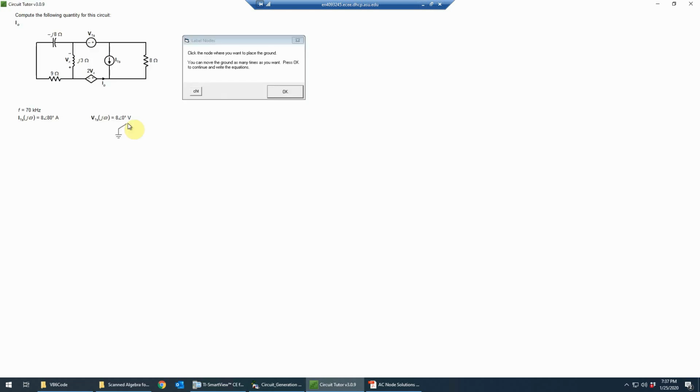And as always, in nodal analysis, our first task is to select an appropriate reference node. Remember that if you fail to select a reference node, then you would not be able to determine absolute values for any of the voltages involved in the problem. We usually want to place it attached to as many elements as possible, and preferably to voltage sources.